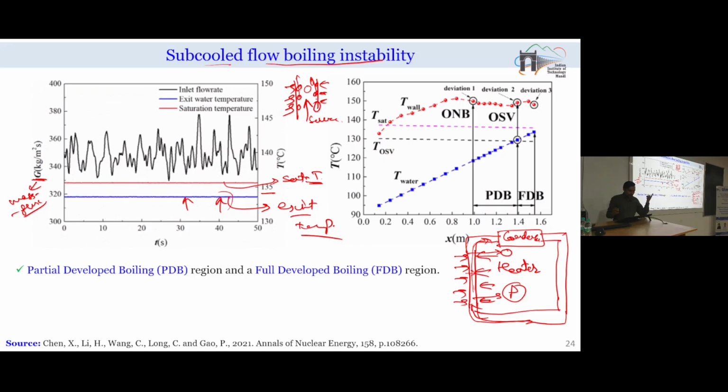Now, as I told you, we will not have a constant value of the flow rate; we will have an oscillatory flow rate. Here you can see this mass flux is of oscillatory nature; it is not fixed. So, if I have to apply this in any practical scenario, I need to design the system in such a way that the amplitude of these oscillations is as low as possible, and I should be able to get some unique average value of the flow rate during the entire period.